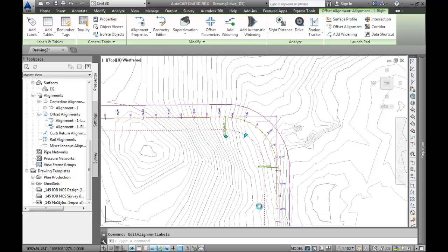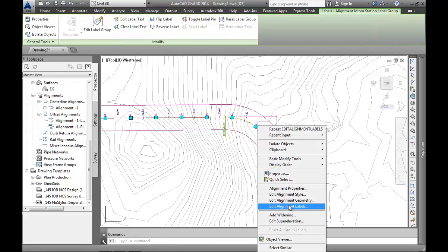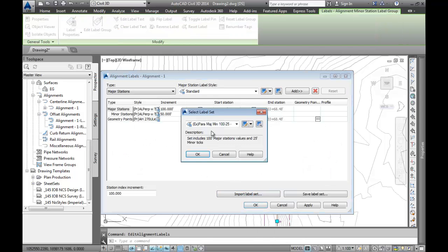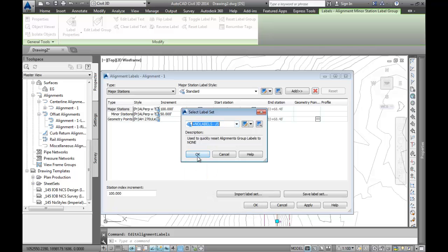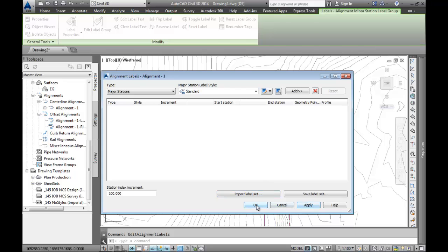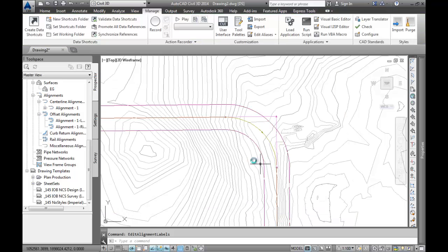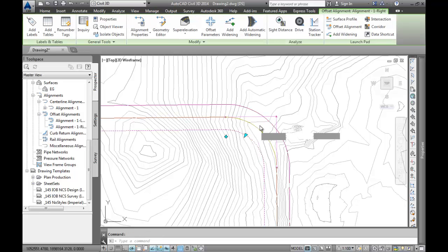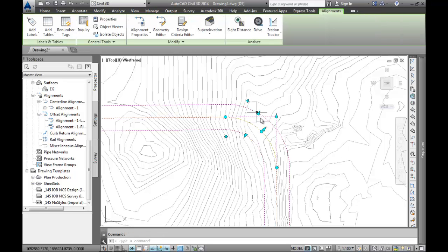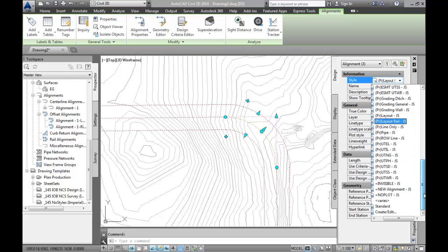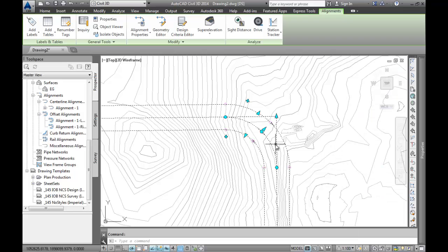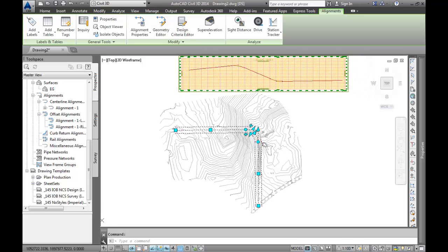We want to remove every reference that we can to every kind of style that we can before we do our Wblock. So we're pulling off all of that. We'll grab all three alignments since we can do these all at once. Change all the styles to standard. Now they're only going to be using Civil 3D. They're not modified in this template.